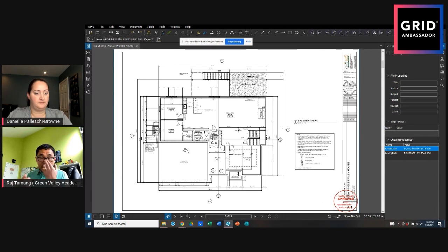You have to think about it, not just when you design the whole building, what we call gravity load, which is the live load, the people living in the house, and the dead load, the weight of the structure itself. In our area, there is also snow load, right? You have to consider that in the design.